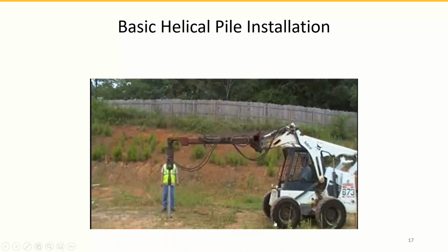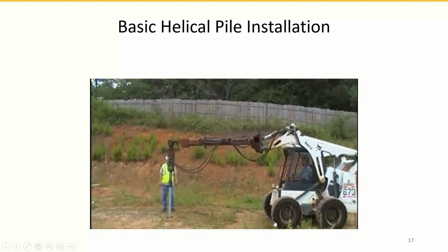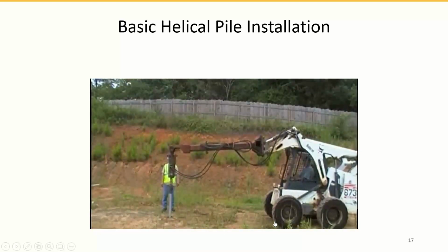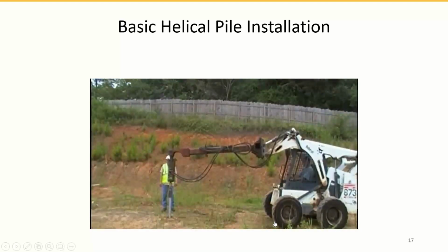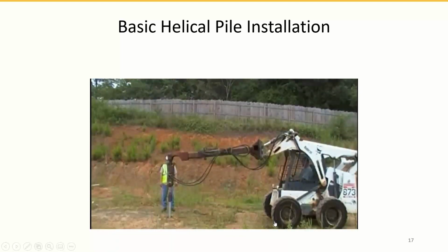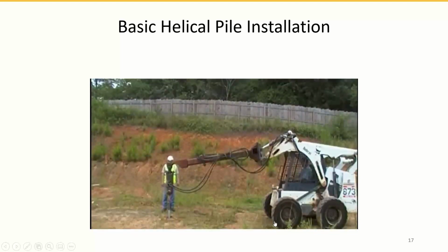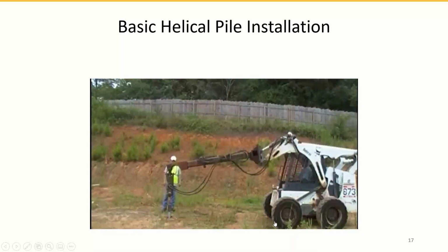And you see there is no spoil, there is nothing. If they were doing this for a real project, they would be installing, like I said, maybe 40 or even more piles a day if there is no obstacle during the installation. So he's going to push that one all the way to the ground. Then he's going to bring a 3-footer extension and install it. Keep going. So this is the lead section that went in first, with that single helix. The lead section only has one helix.